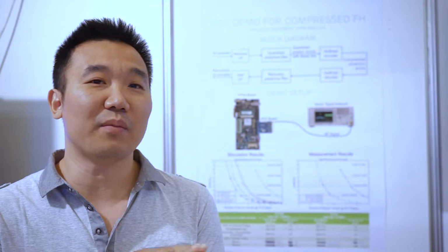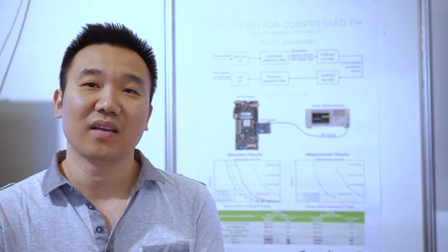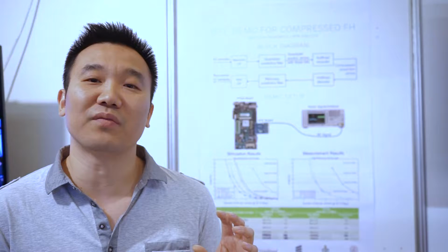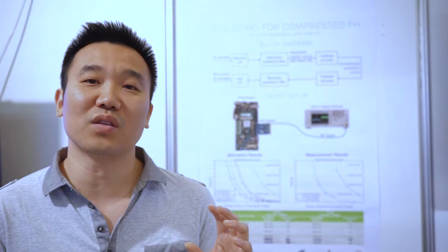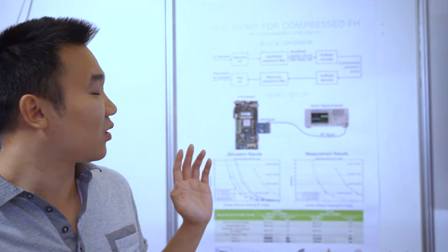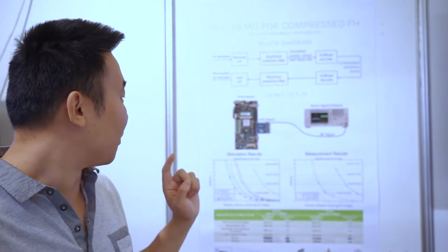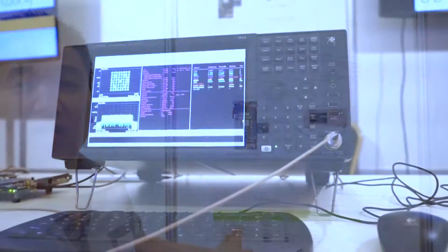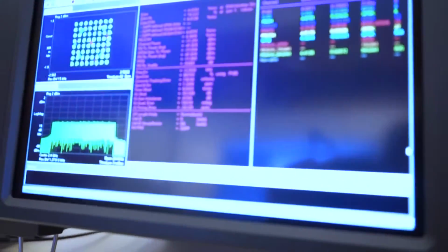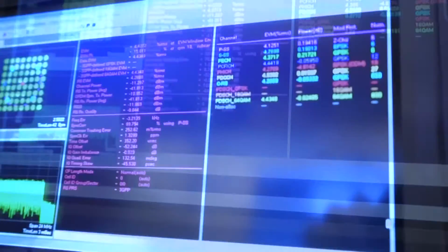We have observed in the current fronthaul link that there is a lot of redundancy in the samples. So basically, we try to improve the CPRI, the time domain fronthaul used in CPRI, with IQ sample compression. The first thing we have derived is a bound. We have derived a lower bitrate bound for fronthaul. Then we know it is possible and achievable to achieve more than 5 times compression.